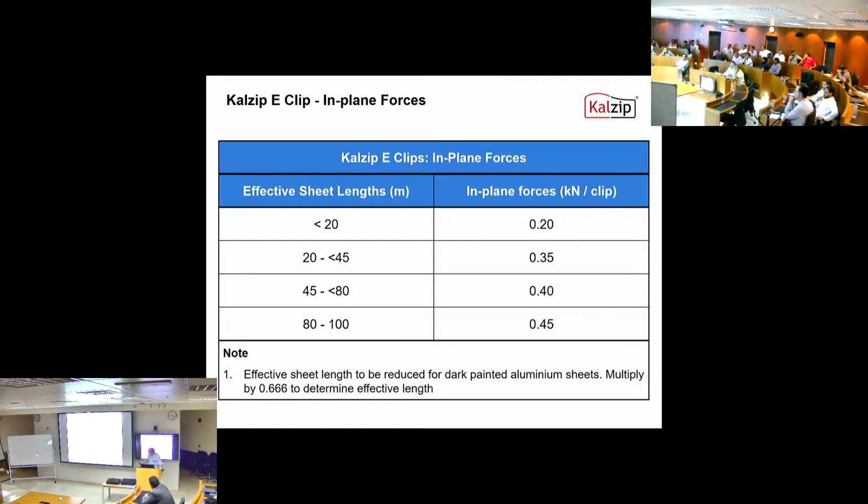Well, this depends on the details you design at the soakers, or the penetration details, making sure you're allowing enough movement, because the soaker should be a two-piece, with an inner piece and an outer piece. The outer piece would be the cowl zip, and that should be able to slide and freely expand and contract around the penetration. Depending how many wells and where they are, you could put the fixed point where the wells are and allow expansion, reducing the amount of movement. So expansion would take place up at the ridge condition and also at the eaves condition. So there are different ways.